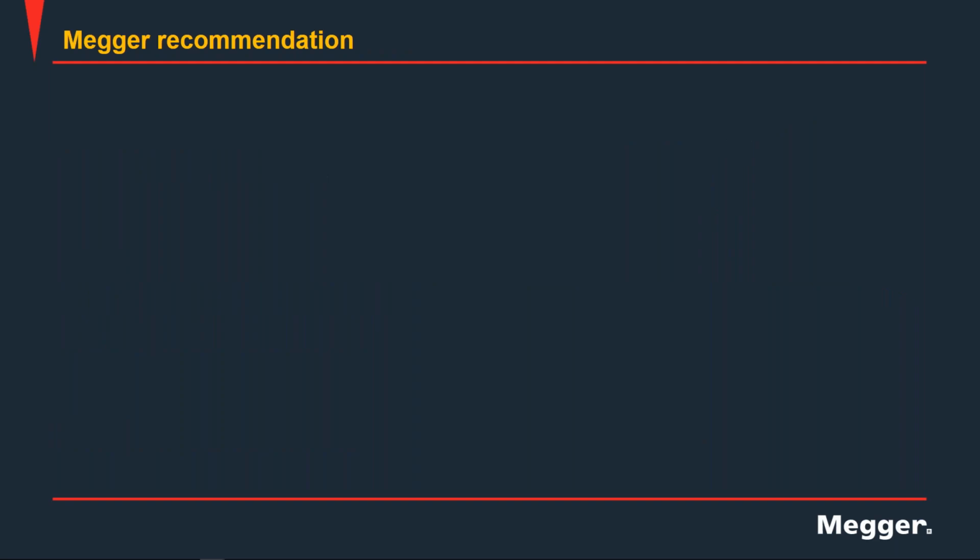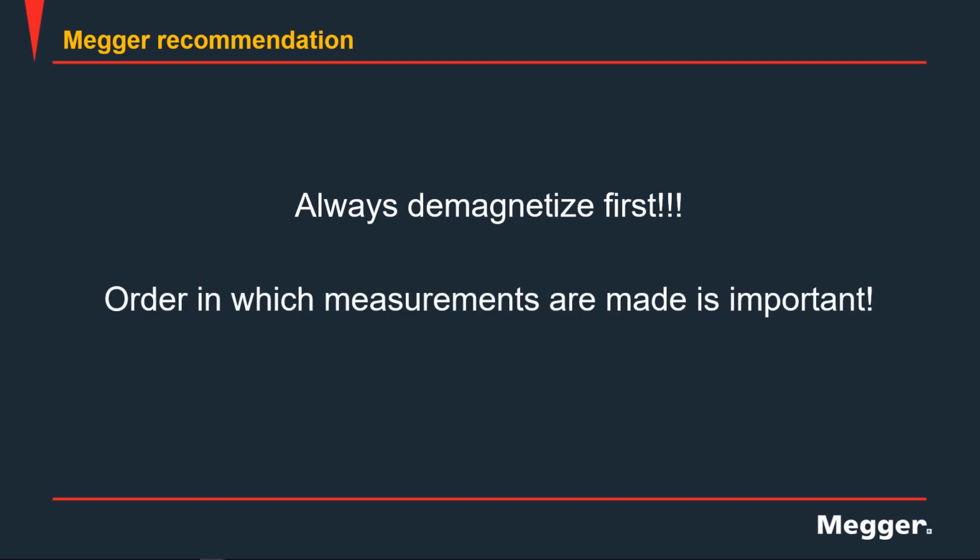And it is our recommendation to always demagnetize your transformer. Whether you're going to put that transformer back into service or do testing, you should always demagnetize. You don't know if there were any solar flares that came by that could have magnetized the transformer. You don't know what part of the cycle the transformer was in when you took it out of service. And if it's a transformer that, say, has been sitting in your yard that is going to be put back into service sometime soon, you don't know what the last testing done on that transformer was. So you will want to demagnetize first before you perform any other measurements.